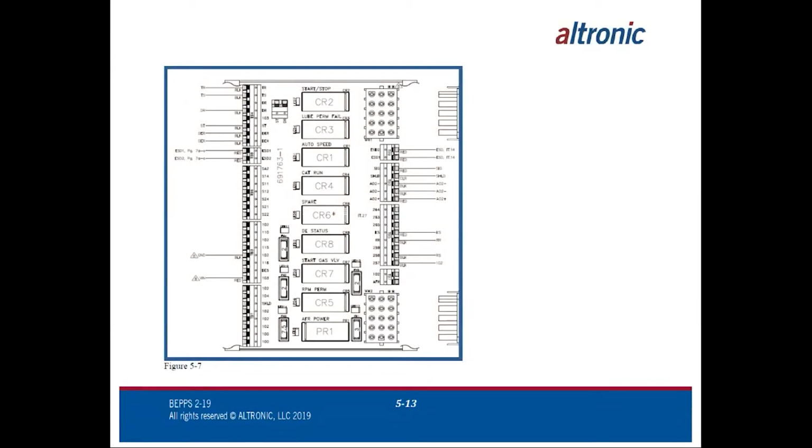Two reasons this was developed. Speed of assembly, speed of delivery to the customer, as well as improved reliability, because it reduced a lot of human wire connections that we would normally find in a panel. It also cut wiring time on the panels down in half.